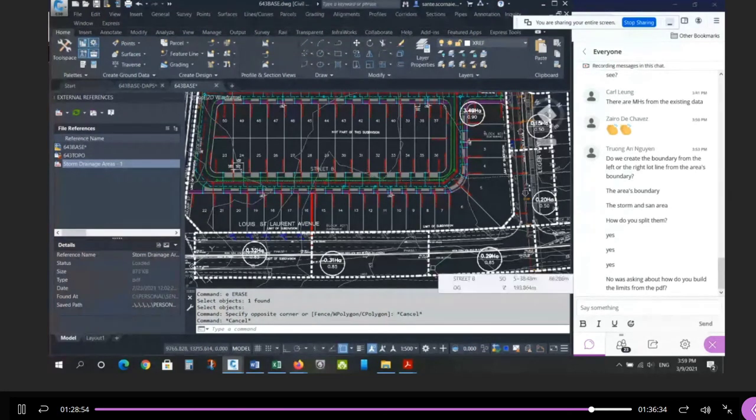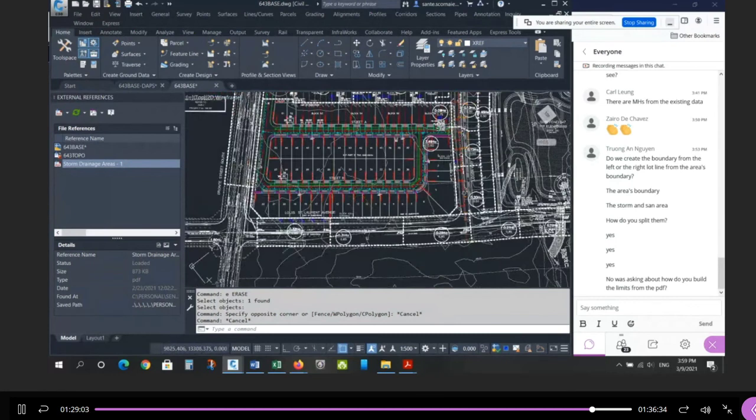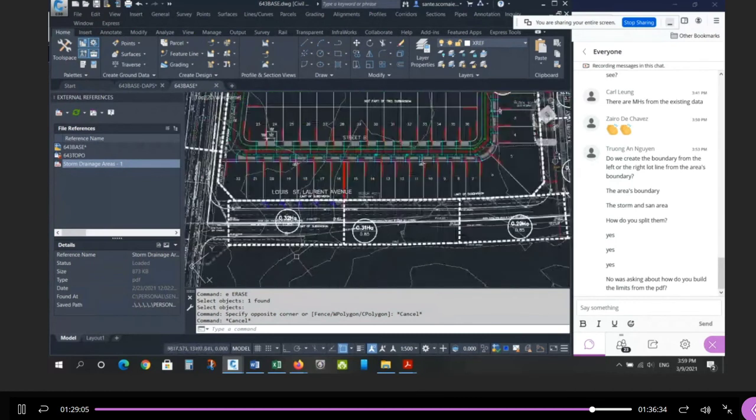Yeah, so we just assume that it will flow to the south side regardless. Yeah, we're designing a sheet flow. Okay, thanks. Yeah, and then we'll check it. Hopefully it works. I haven't done this before. In the past, I've actually put in rear lot catch basins over here to bring the flow back inside. But I'm going to try bringing it.